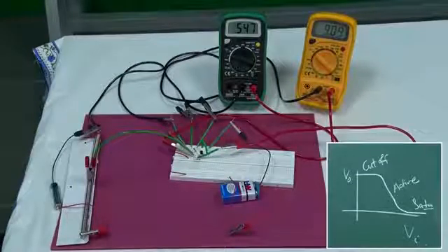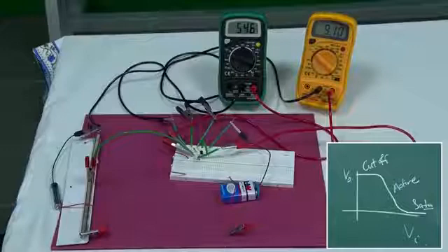So, we are moving towards that active region. So, the transistor is now conducting, there are carrier injections from the emitter to the base, there is some IC, and there is some RL into IC drop on that 10 kilo ohm resistance, and therefore, the output voltage of the collector has gone a little bit down.